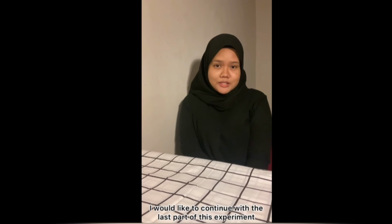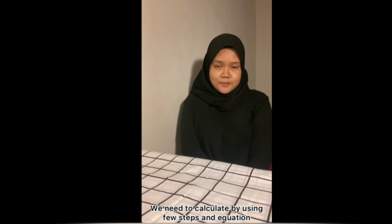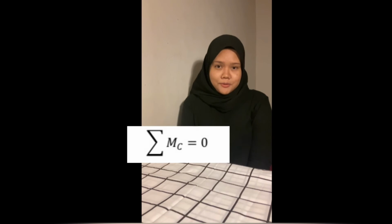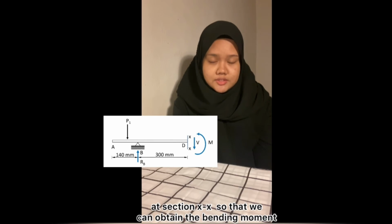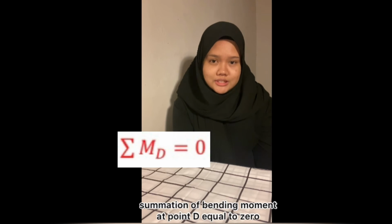Let's continue with the last part of this experiment, which is to prove the superposition principle for bending moment. After we obtain the measurement for bending moment, we need to calculate using a few steps and equations. Firstly, we need to obtain the reaction at point B by using the equation summation of bending moment at point C equals 0. After that, we need to make a cut at section XX so that we can obtain the bending moment by using the equation of summation of bending moment at point D equals 0.